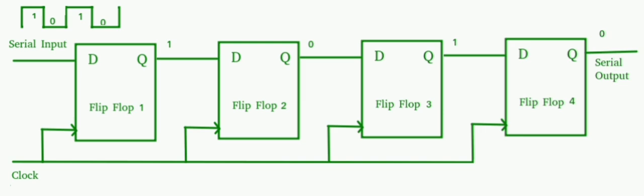Dual slope integrating type ADC. The total number of clock pulses required = 2^n + N, which equals 2^(n+1) at full scale. It is the most accurate ADC, therefore mostly used in digital multimeters. It is the slowest ADC. A dual slope integrating type ADC is used in a digital voltmeter. Remember, digital voltmeter means dual slope integrating type ADC.